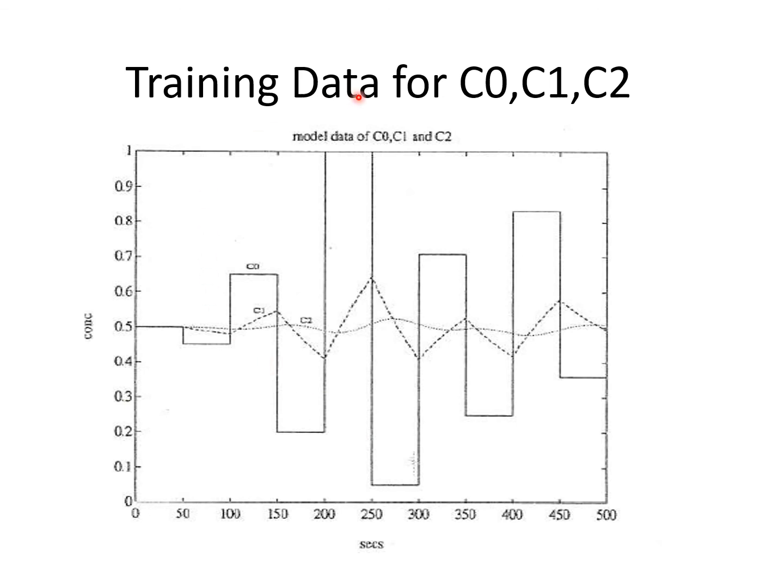And this is what we mean by the data set. Okay, this is the training data set to train the network. So this is how we excite the input. The C0 is in this form, multi-step form. Okay, and that is C1, the concentration from the first tank. C2 is the concentration from the second tank. So C0 is the input, C2 is the output, C1 is the intermediate tank.